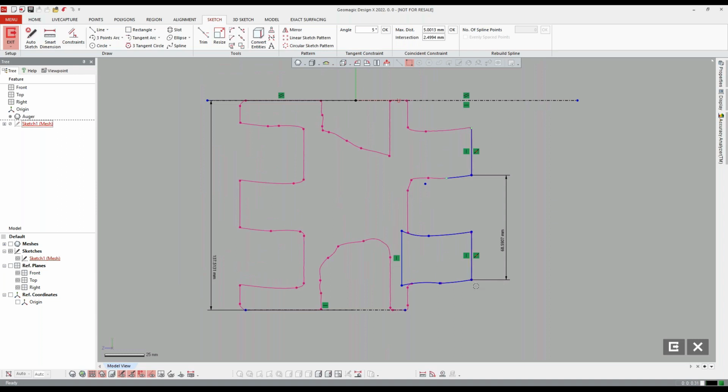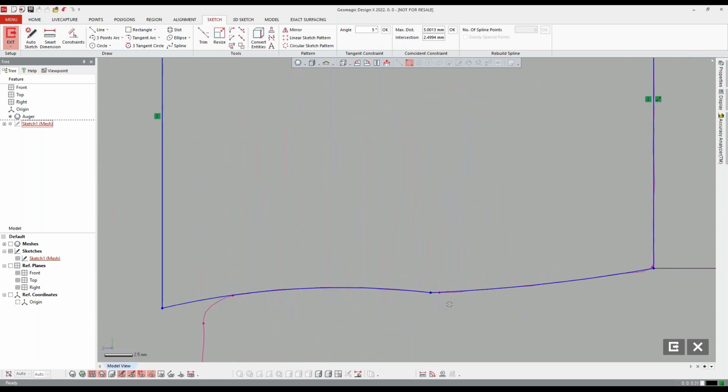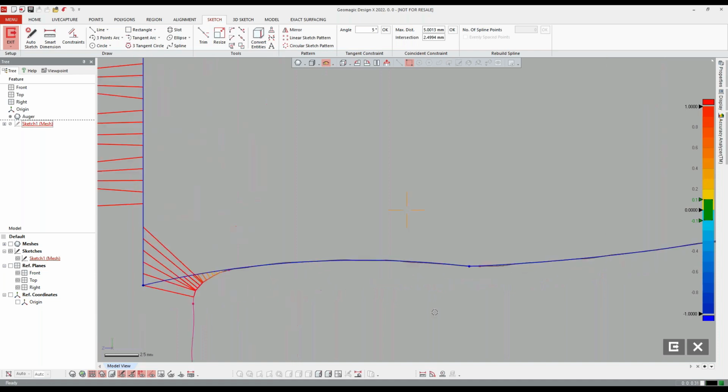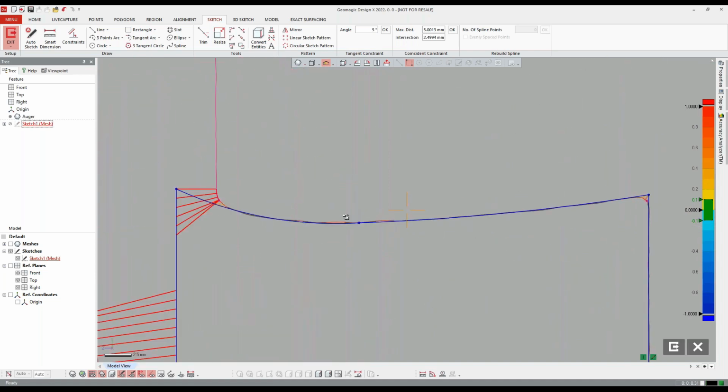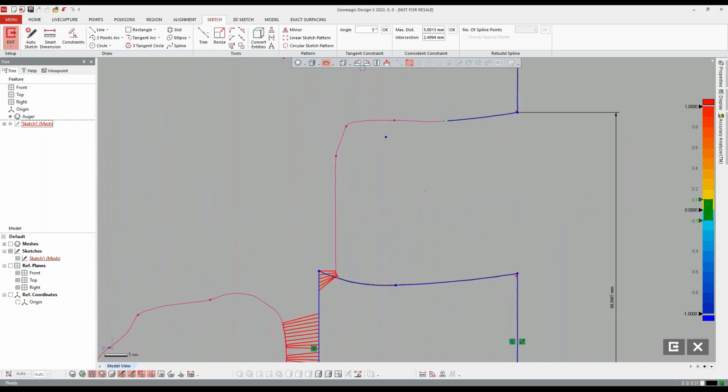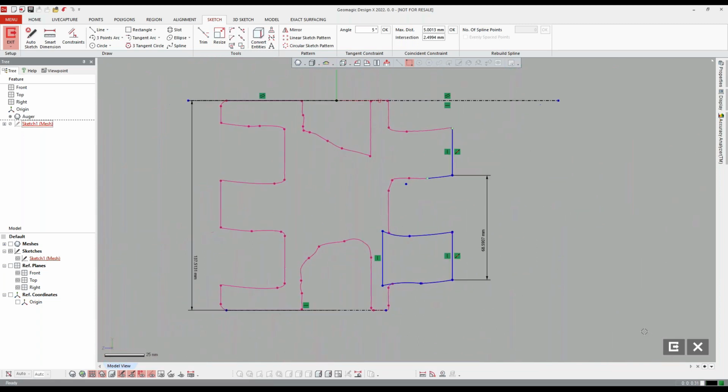So we've got the profile, I've got a start point here, I can start from here, I've got what my pitch distance is, and everything's at the right height already because we drew the stretch right on the mesh. So I don't have to guess about that. I don't have to guess whether any of this is going to fit. If I wanted to adjust anything in Sketch, obviously I can come in and do that, or use Accuracy Analyzer. While I'm in here, if I thought anything was grossly displaced, I could readjust, but it's all pretty tight.